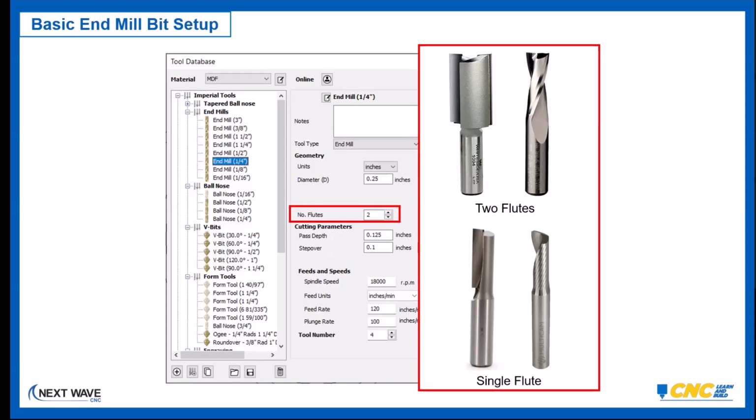So I usually recommend people, especially with these smaller tools that don't travel super fast, to go with a 1 or 2 flute bit. I use both, and for a lot of work, I prefer this bit right here to the right, which is one of my workhorse bits. And then for some cutting, I have that one. And then I have this large 2 flute one for some larger cutouts. So yeah, all 4 of those I have in my inventory, depending on the diameter and what I'm cutting. And we'll talk more about that later as well.